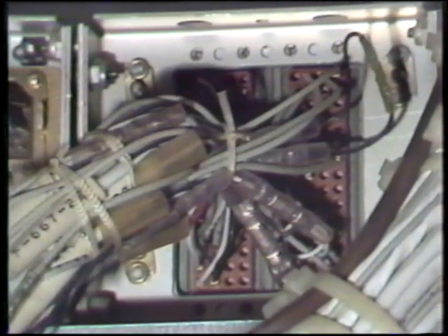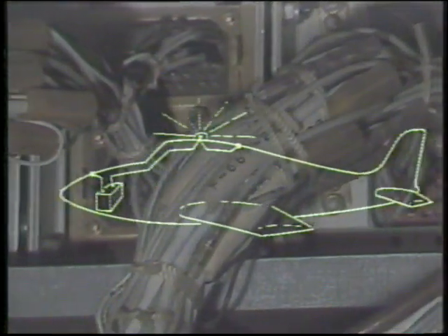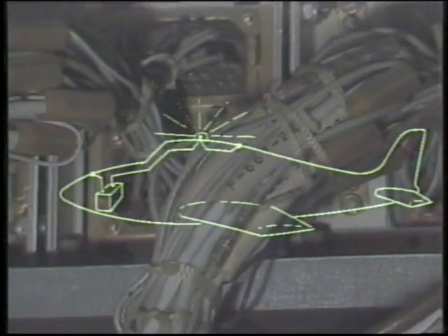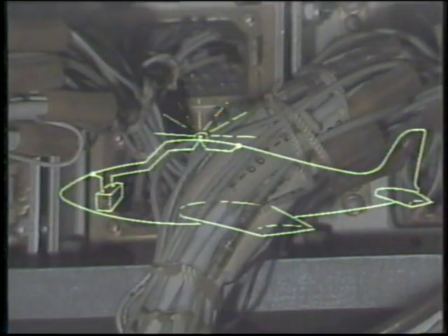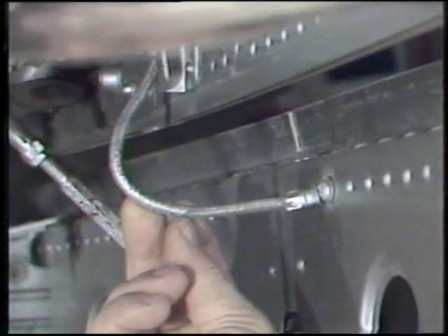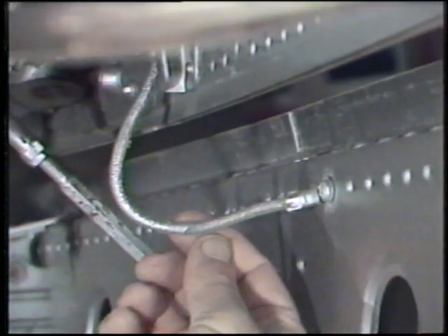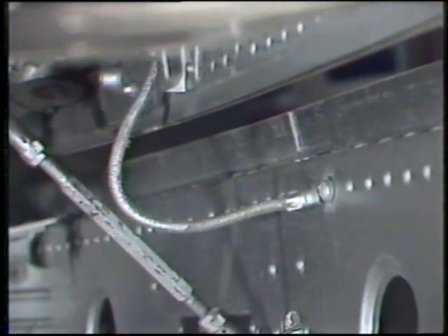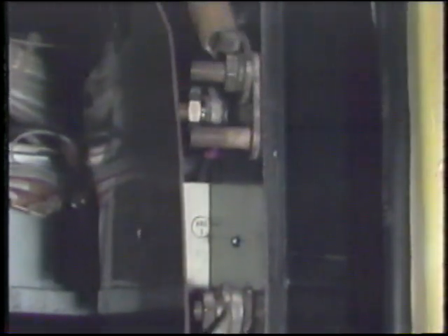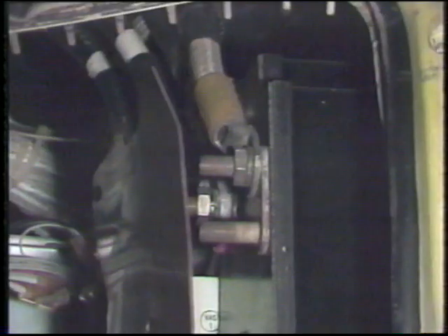A single-wire electrical system used in most aircraft uses the aircraft structure as a return path between the load and the source. Using the airframe as a return path requires a low resistance path between the different parts of the structure. The single wire eliminates the need to run a separate wire as a return path, thus saving weight.